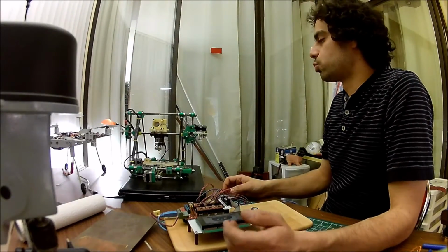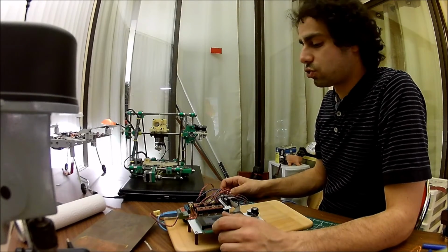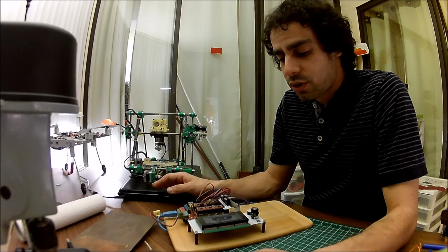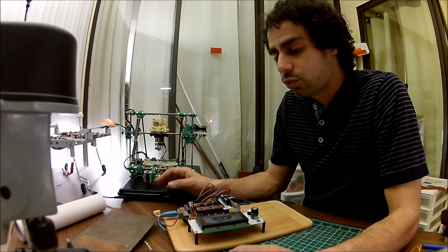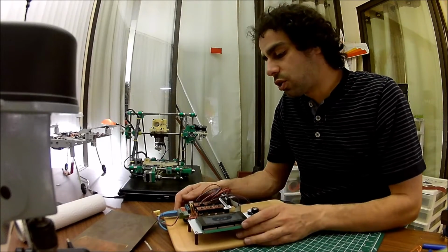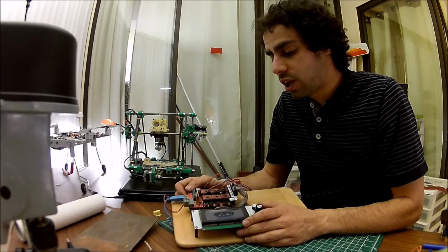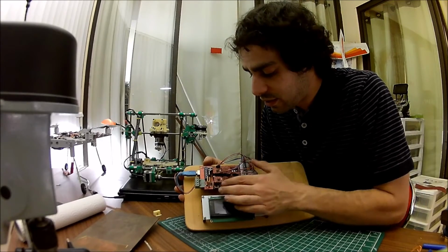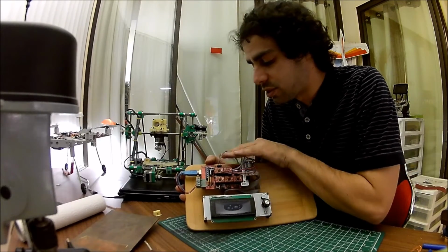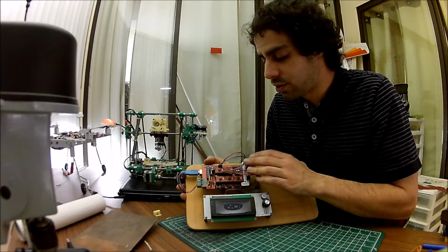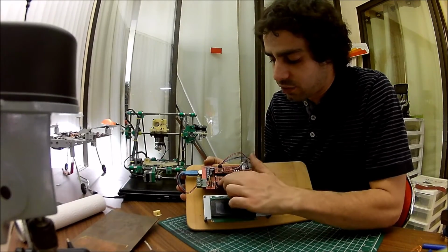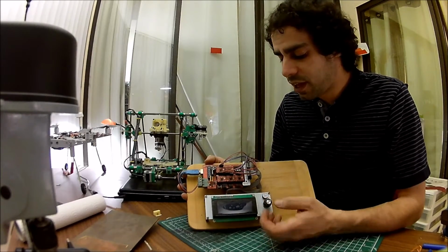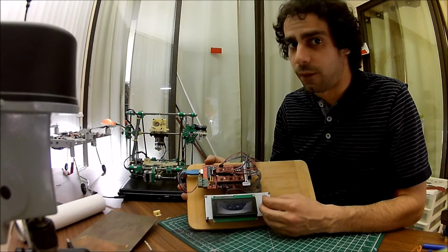The actuation and extrusion process of 3D printing is controlled through electronics and your personal computer. Your computer has software on it that converts your 3D model into G-code, and then the G-code is executed through the electronics of the 3D printer, which consists of a microprocessor and a bunch of motor drivers. Oftentimes these days it's Arduino based. This example is Arduino based, and here you can see the individual motor drives. There's also a graphic interface that allows you to select which files you want to print, and other basic properties of the 3D printer as well.